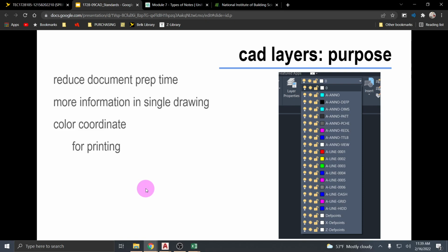So there are a couple of different file types in AutoCAD, just like you have a Word document versus a PDF file. You have AutoCAD drawings and you have AutoCAD templates, and then you also have AutoCAD exchangeable files, which are ones then that we can export our line work into software like InDesign or Photoshop or in my case, I do a lot of it with Illustrator, so that way I can laser engrave things.